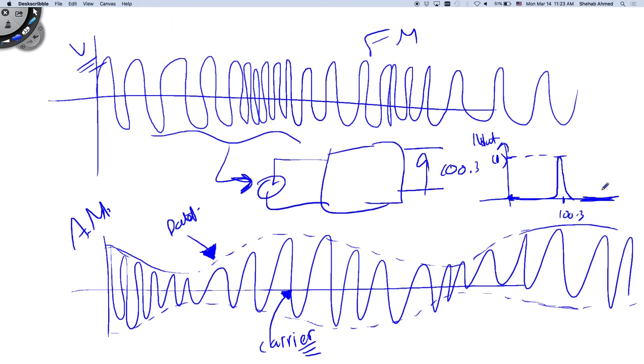This is sort of drawing the transfer function. This is frequency. At every frequency, I plotted the magnitude of the output, and I want to do the same thing here. So this is frequency, and this is magnitude of the output. How would this look? At low frequency, I want whatever's coming in to come out, so multiplied by 1. So 1 at low frequency. And then at high frequency, I want everything to be 0. So I will have to figure out a way to design a circuit to do this.